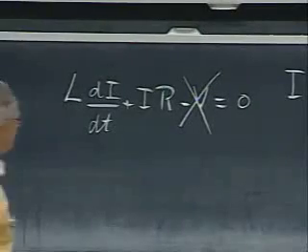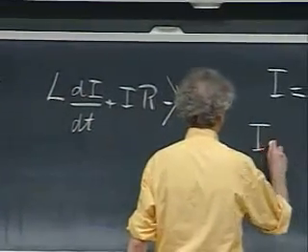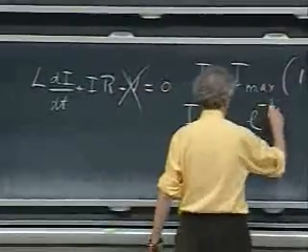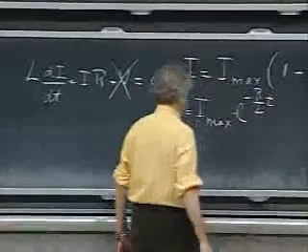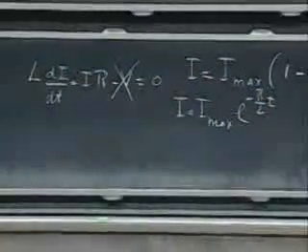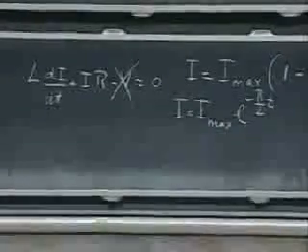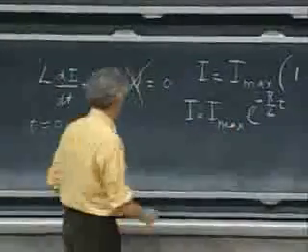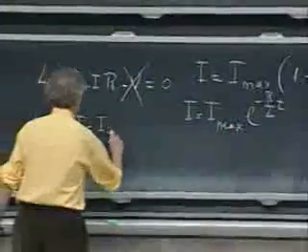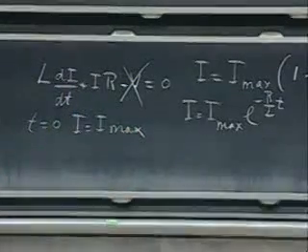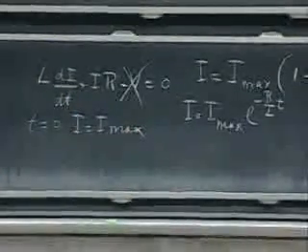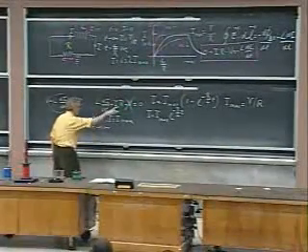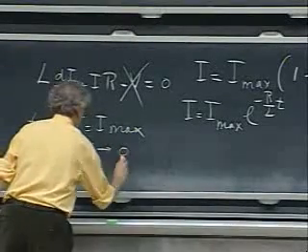And the solution to that differential equation is that I, as a function of time, is I max times e to the minus R over L times t. And that exactly has all the quantities that you wanted to have. Because notice that at t equals 0, the current is indeed maximum. And that's what you require. That's the moment that you make that capital V 0, the current was still running. But notice that when t goes to infinity, you wait long enough, the current goes to 0.